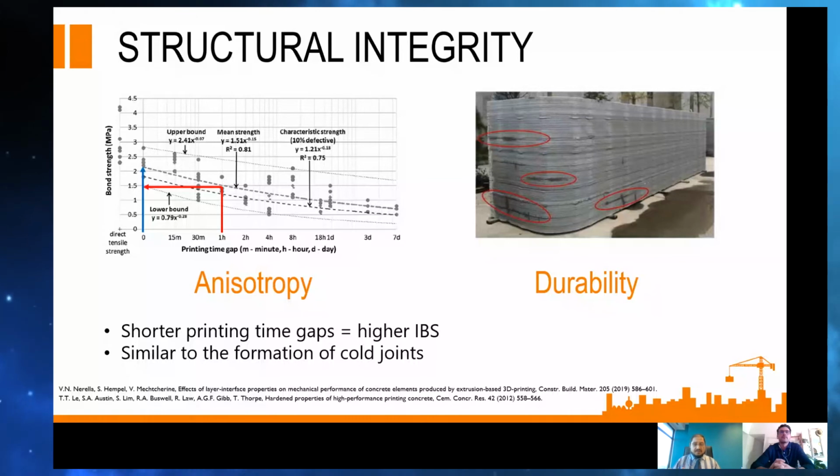And then just obviously, for those who use conventional concrete, when it comes to your mix design and casting on site, you normally take cubes and test the cubes to test the strength. Now, this is not your conventional concrete that you pour. How do you take cubes, or do you make your own cubes, or how do you test the strength of concrete? Maybe pocket core at the end of the day. So what we do is we print sample objects, which we then either saw cut prisms from, or we core elements out of it and test it. So for compression, we core samples because we want an aspect ratio L over D of 2 to adhere to your code specifications. And then for flexural samples or direct tensile samples, we use strips or ribbons that we saw out of, say, if you look at this figure on the right of my screen, you would saw a piece out here and then you test it.